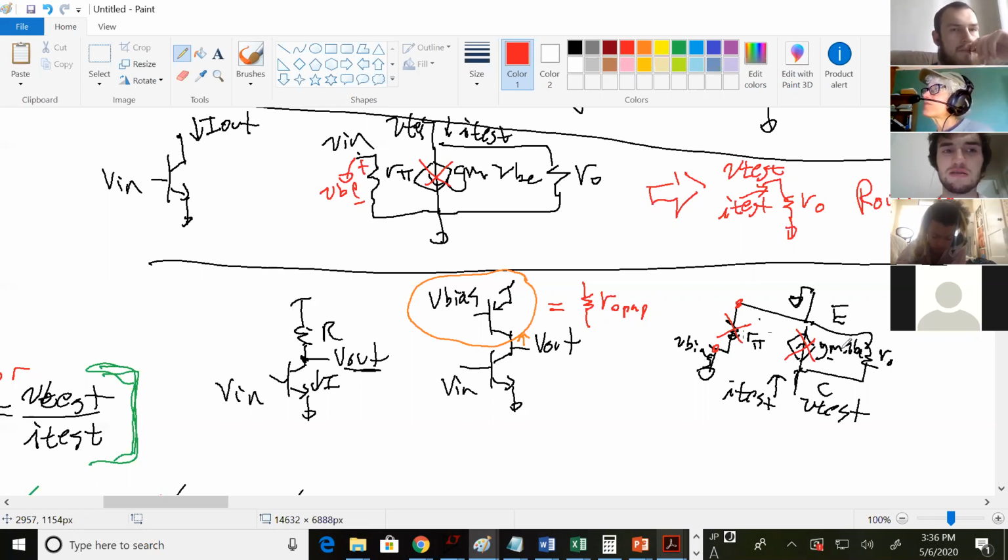For those, it's operating voltage. The VA's a characteristic of the transistor. So VA never changes, but what does change? VCE. Yeah, and what's that called? When VCE changes and the current changes, what's that effect? Is it base width modulation? Exactly. So RO represents base width modulation.